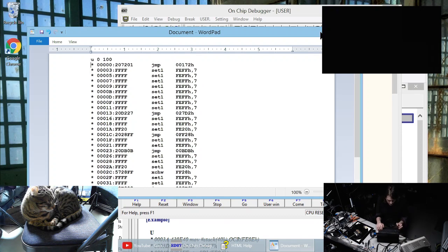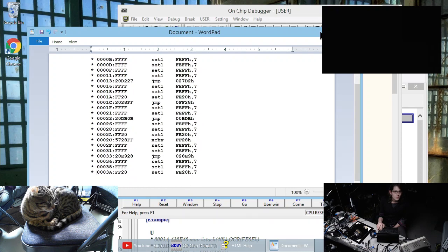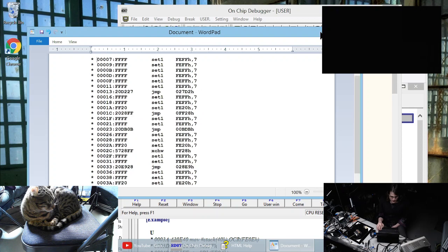And so this starts off fine. We've got a real reset vector, and then here's another vector. There's an interrupt vector at hex 13, another one at hex 1c, and if we looked at the data sheet, most of these are in the data sheet. I say most of them. Well, I guess both of these firmwares have a little bit of undocumented hardware. The Wacom firmware has its Wacom scanning engine, and the debug dongle has the one-wire communication hardware, which both seem to be somewhat custom.